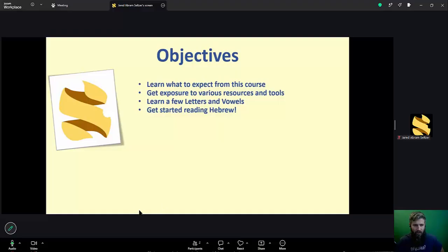Then the main part of this video is going to be how to use the Annotate tools so you can draw on screen. One of the ways you can annotate is by clicking the button on the top here and selecting Annotate, which causes a toolbar to appear on screen. Another way is using this icon that looks like a pencil. Click on that and the same toolbar appears.